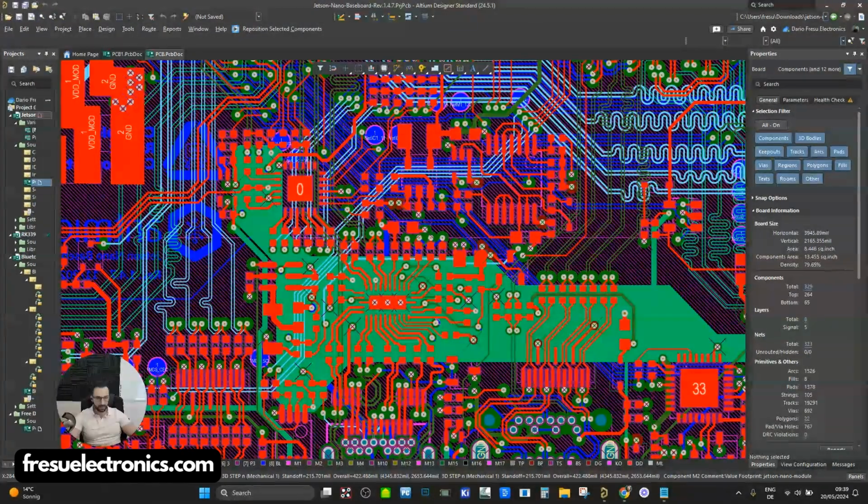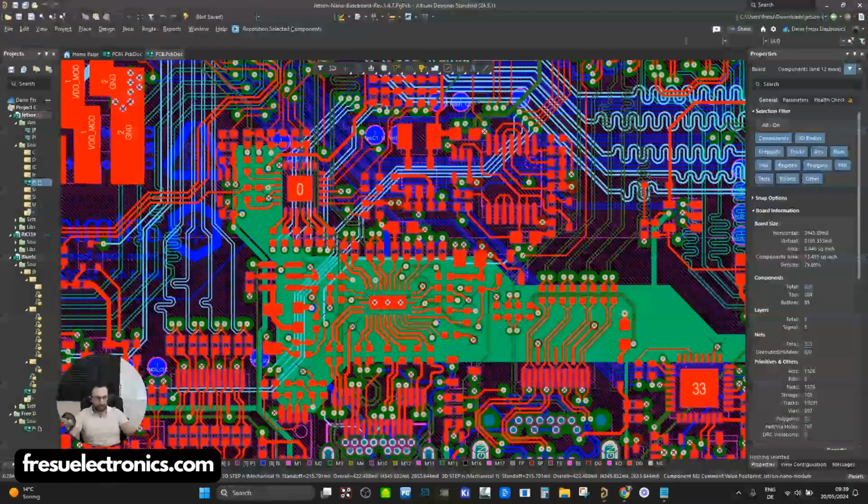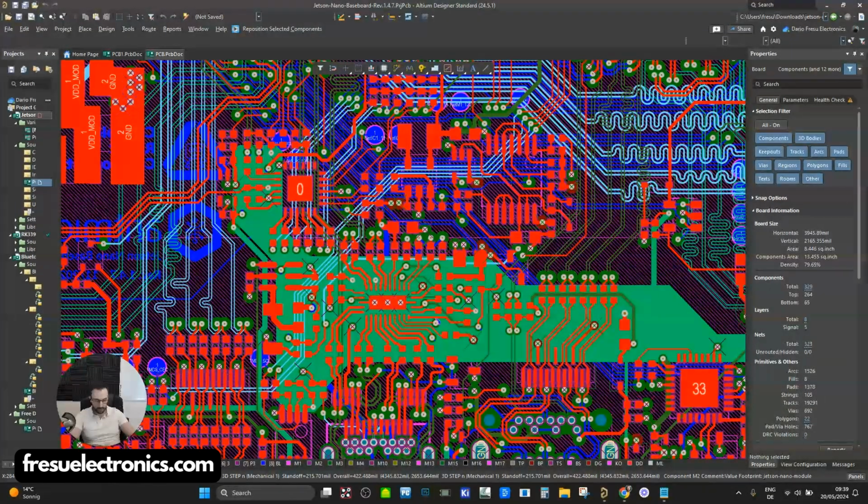So one of the ways that we're going to achieve this goal is by choosing the right decoupling strategy. And what do we mean by that? We need to choose also the decoupling capacitors that serve several functions. One of the functions of the decoupling capacitors is actually to reduce the dependency from one integrated circuit to the other. Why is this important?